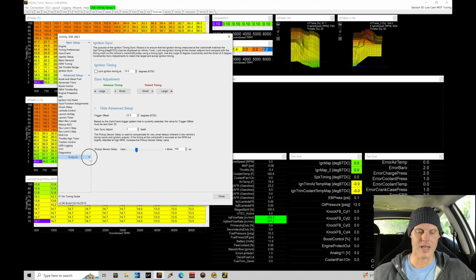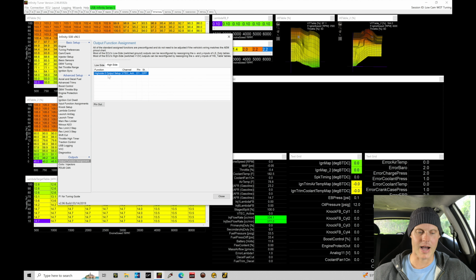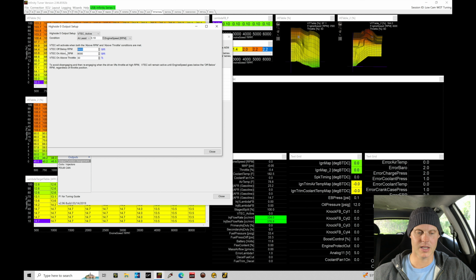If I jump into the outputs and go into high side, I can set my VTEC engagement so that I'm at 3,000. So I'll set my off point at 28. I'll set my on point at 3,000. And we're not going to permanently keep it there. We're just doing that so we can get onto the high cam easier and stay locked onto the high cam.